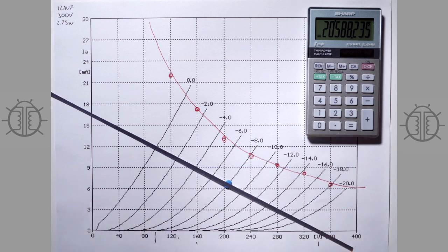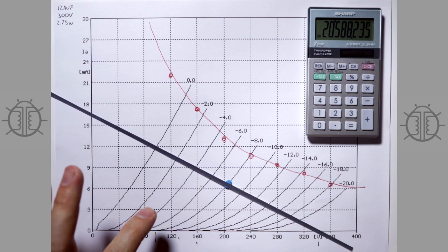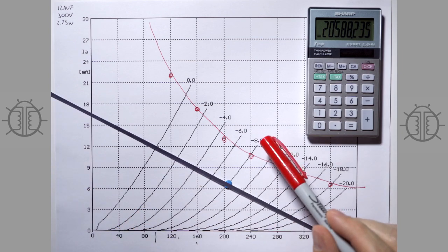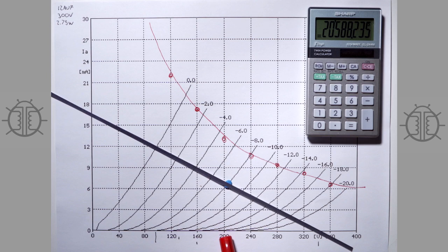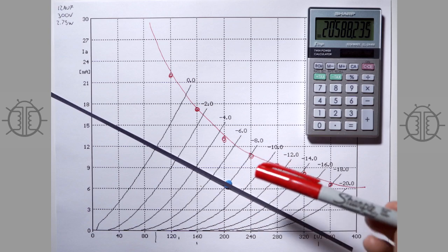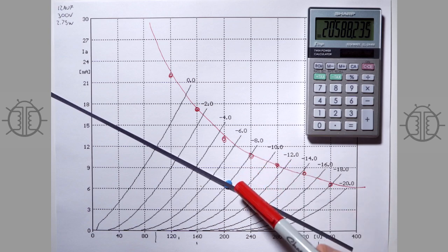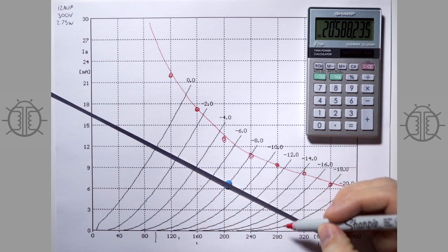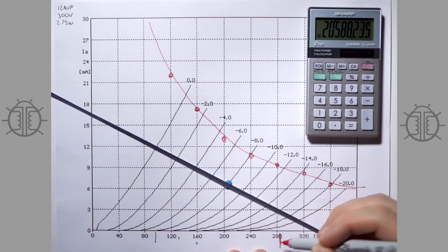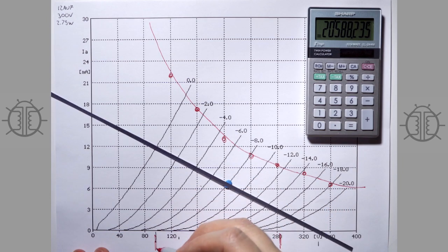So now keep in mind, this is what you should look for. So this is your operating point. You're at -8 volts between the grid and the cathode. You're going to have 200 volts on the plate about. And you're going to be able to swing, if you put your voltage in, and it's plus or minus 8, if it's 16 volts peak to peak, so it can go 8 down and 8 up, you're going to end up with your swing being something like this.